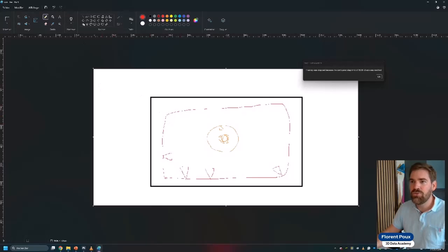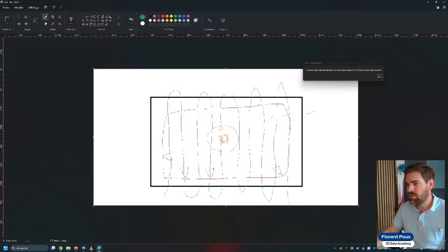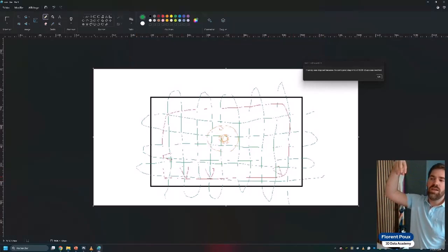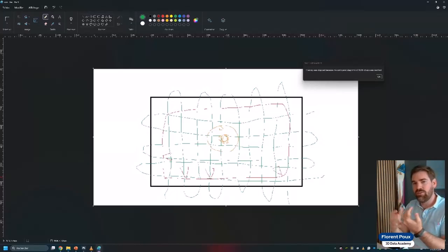In cases where you have large fields, usually with a 360 camera, the path that I recommend is this one. Imagine that this is an outside area and that's just the extent. You will do this exactly like with a drone. You go until the end, and this way as well. And you orient the camera maybe down, but not a pure nadir position, because you will not have so much understanding of the 3D geometries. You orient it maybe 15 degrees, oblique, and it will work for you.